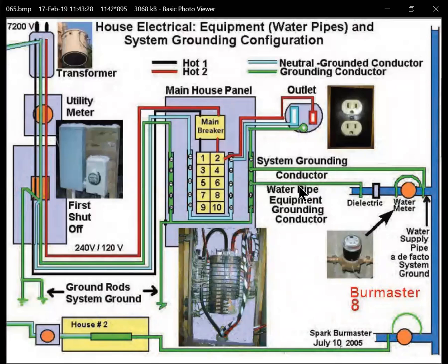the grounding system. And so then the other definition here is the definition of the first shutoff. The definition of the first shutoff is wherever you have the switch, which is right after this electric meter, that's called the first shutoff.